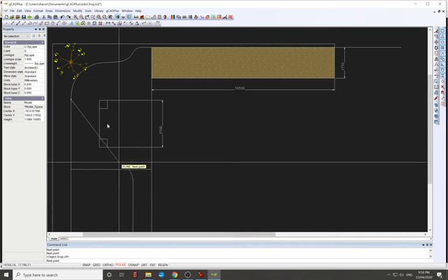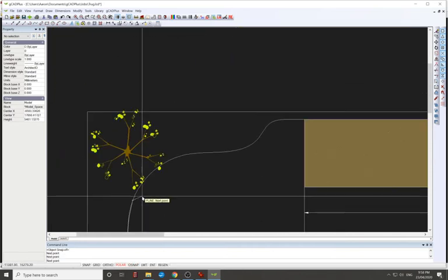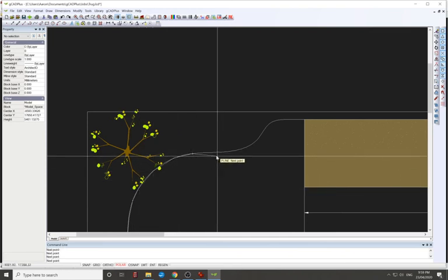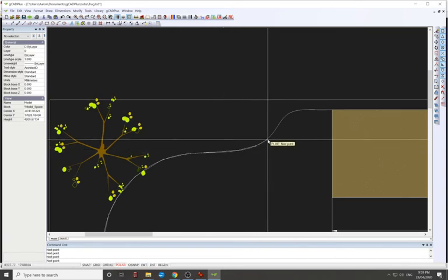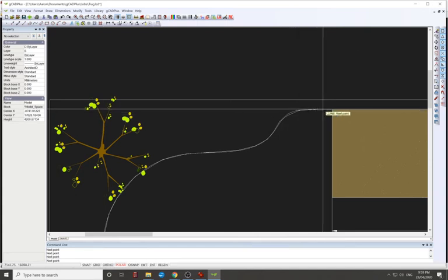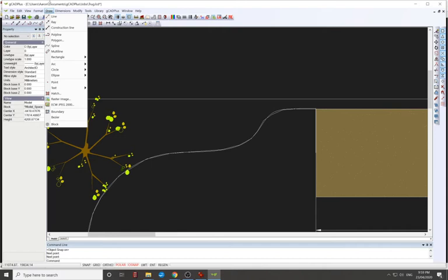We'll turn the object snap off, and we'll go around the curve with the object snap off. It's a bit easier. Just eyeballing it. Probably turn object snap back on, get to there, and then because you can't really ID where you are, I'm pretty sure I'm correct, so we'll enter closed. Might just give it a save.